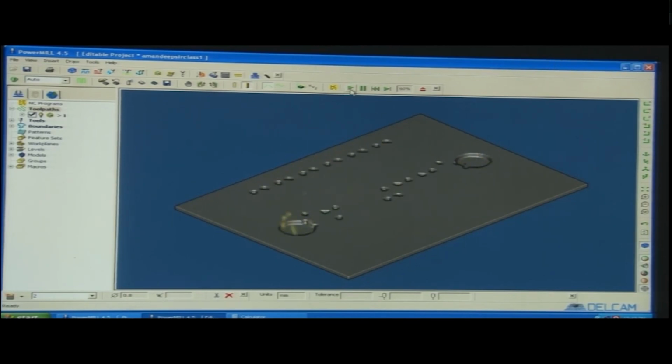So, now the complete simulation, I just press the play button. With this command system, we can get the complete code of the whole job. It is just the plunging. Where does the plunging happen? When we fix the coordinates, you can see this pattern that is built here on the workpiece. In this pattern, at each corner, whenever the tool turns, the plunge happens. The tool comes down or comes out. So, that is being shown in this simulation.